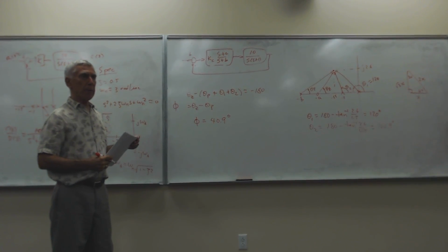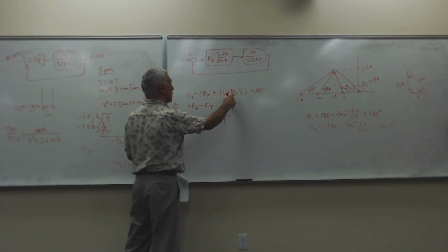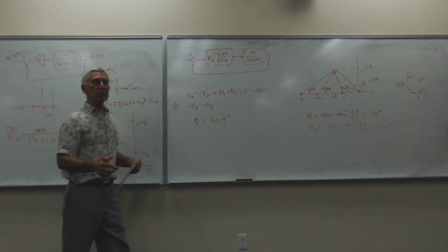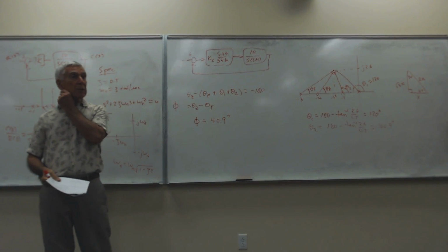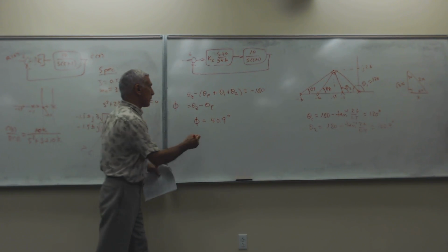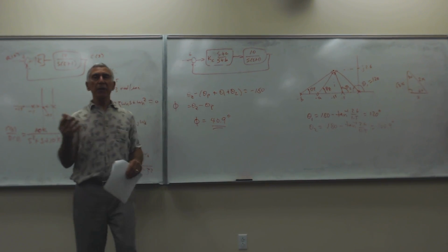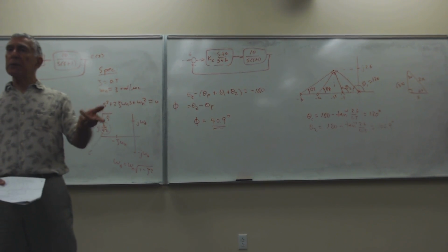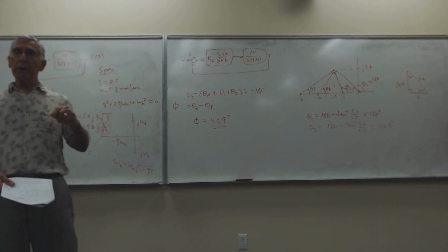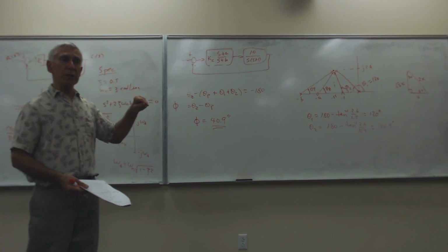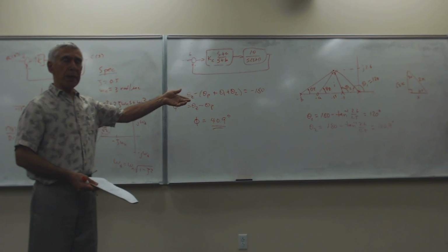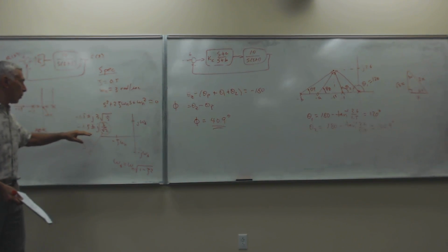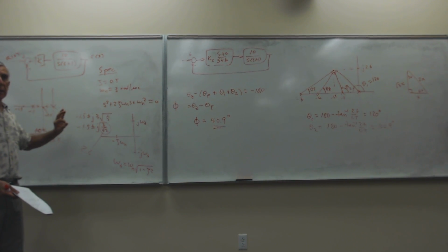Because we know theta 1 and theta 2, all we're looking for is this difference, theta z minus theta p. And so this is the positive phase angle that the lead compensator must contribute in order that the root locus pass through that desired closed loop transfer function pole.